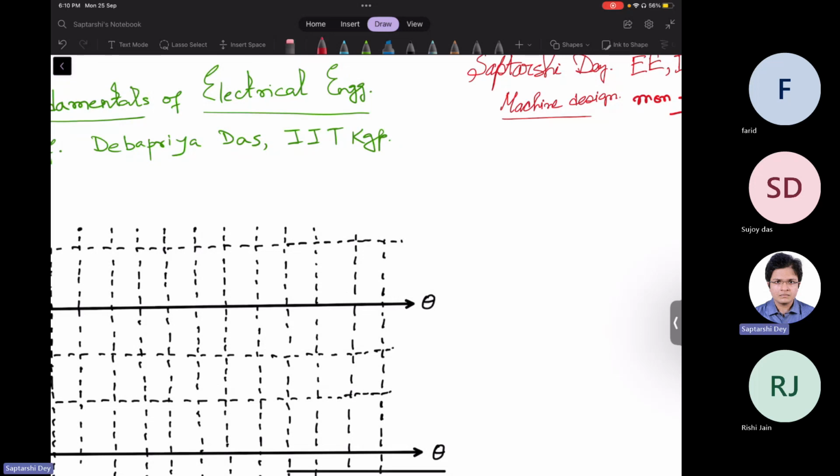That is because it gives the optimum value of power transfer by copper ratio, and other advantages of three-phase motors, and all the three-phase motors came after the three-phase power system came. The instantaneous power of a three-phase system is constant. It's not like a single-phase power which has ripple. Instantaneous power itself for a three-phase system is constant.